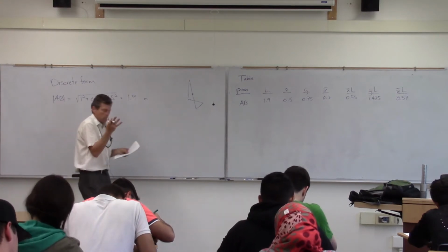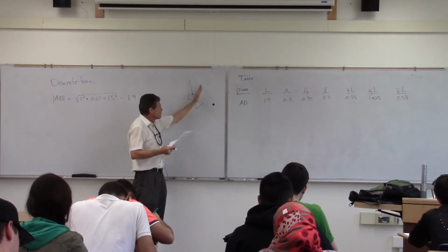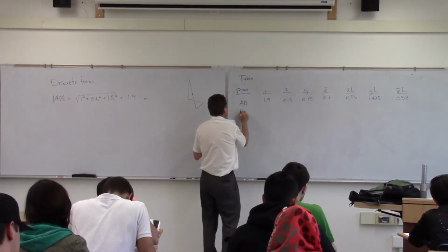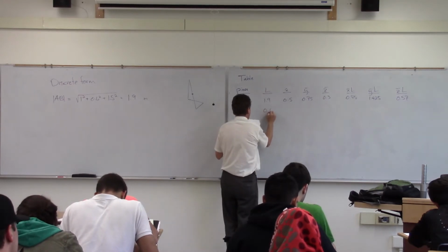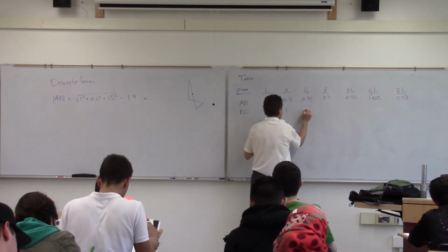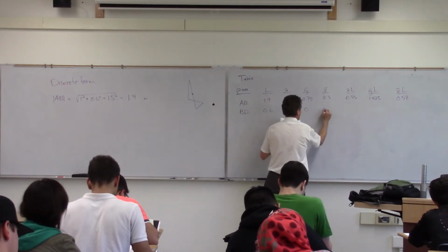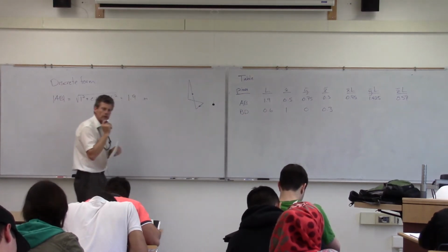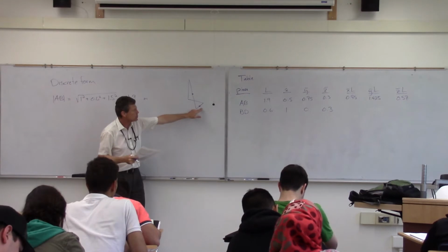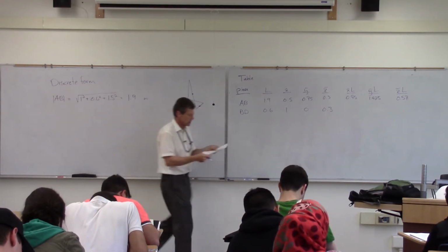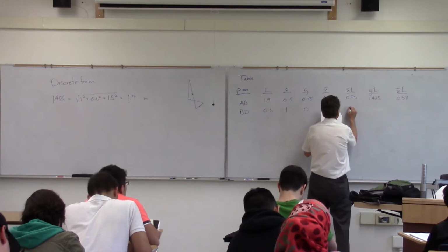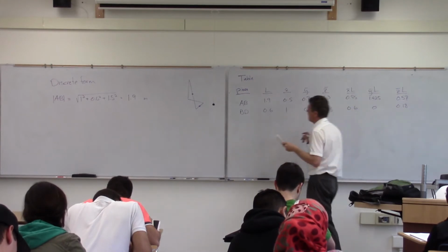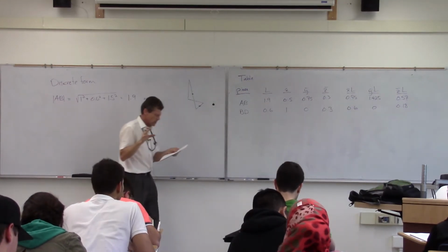Okay, that's piece 1. That's the most difficult one because we have to figure that out. The other ones are all nicely arranged on axes. So our particular piece BD, so BD is this piece here. I'll be looking at the centroid of that one there. So I describe the centroid there in terms of the little x, y, and z centroids there. Then simply multiply that out. Nice thing, we get some zeros in there.